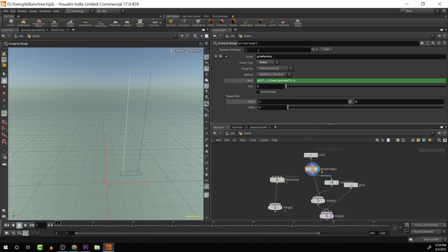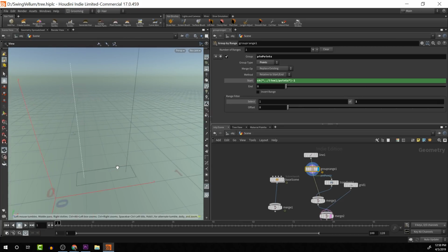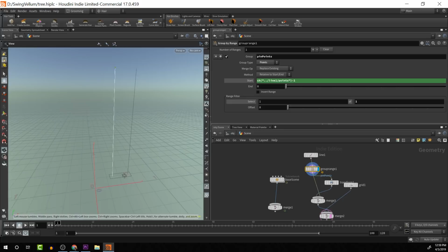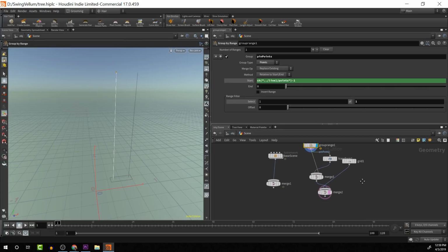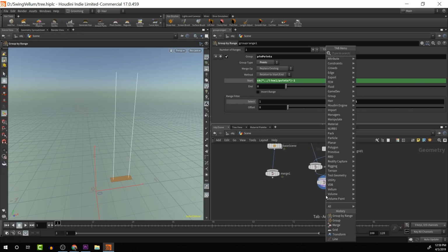So now we can see that we have the pinpoints that we can use for our group. At the bottom over here we have the base, and on the base where the actual swing is going to be, we'll use a different method to connect these two together because we want it to actually be able to move. We just don't want it to be locked into that world space. So the only points that we want locked are these top ones over here. Okay, now that we have that, let's turn this to vellum cloth.